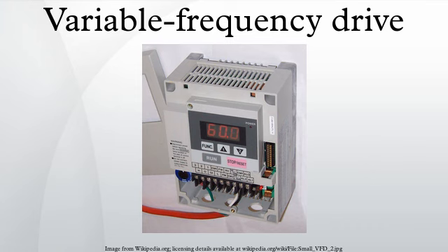In starting a motor, a VFD initially applies a low frequency and voltage, thus avoiding high inrush current associated with direct online starting. After the start of the VFD, the applied frequency and voltage are increased at a controlled rate or ramped up to accelerate the load. This starting method typically allows a motor to develop 150% of its rated torque while the VFD is drawing less than 50% of its rated current from the mains in the low speed range. A VFD can be adjusted to produce a steady 150% starting torque from standstill right up to full speed.